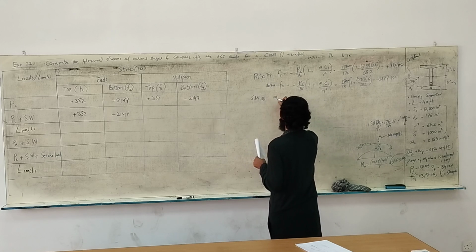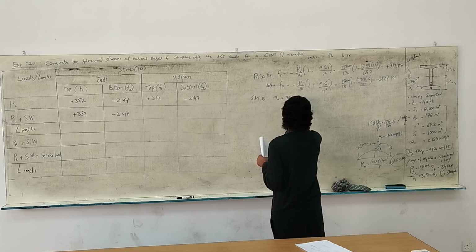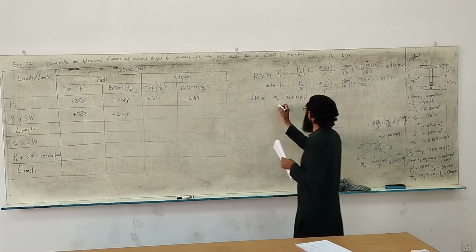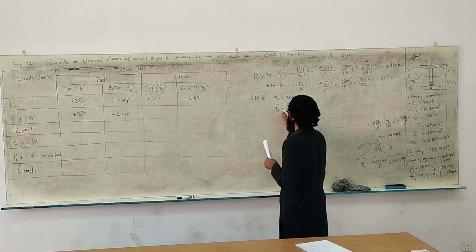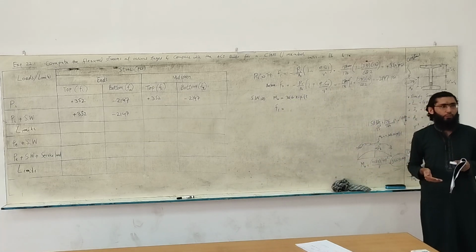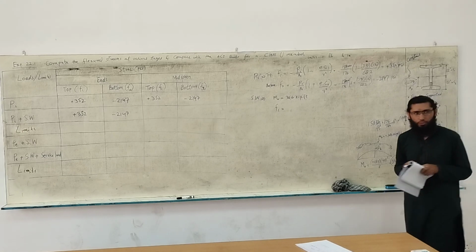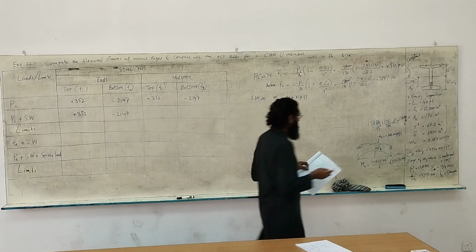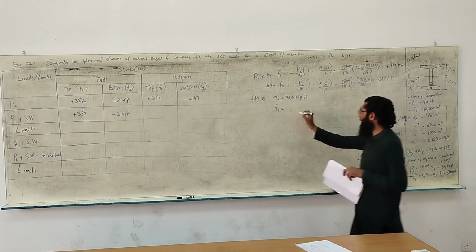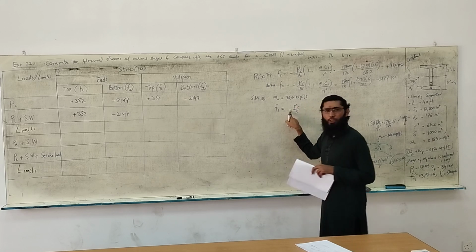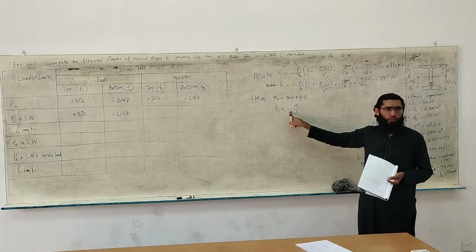So the moment was 36.6 kip-feet, and now the stresses due to this would be, as you can understand, tension at the bottom and compression at the top. So at the top we should see compression: minus M naught over S. I'm using this minus because I know that at the top it will produce compression.